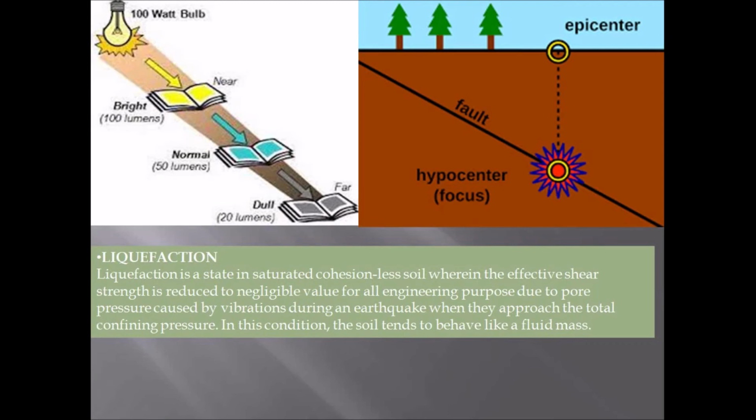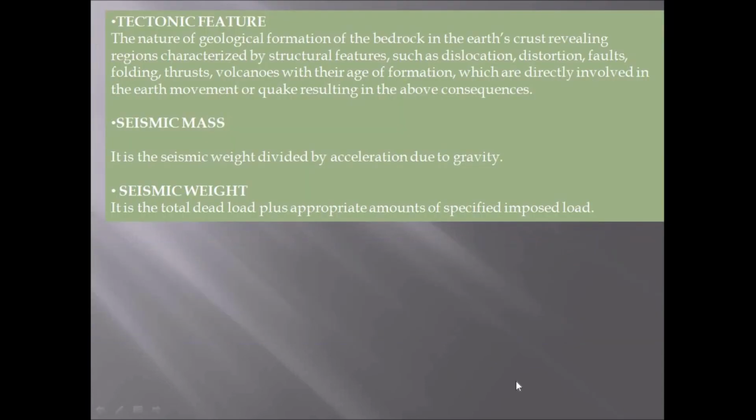So basically, when the earthquake load acts upon a saturated cohesionless soil like sandy soil, the soil at that place loses all its shear strength and behaves like a fluid mass. So at that site, it is very likely that the structures constructed over that soil collapse. So liquefaction is very, very dangerous.